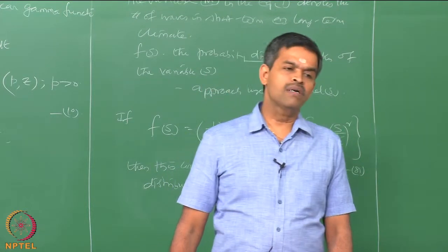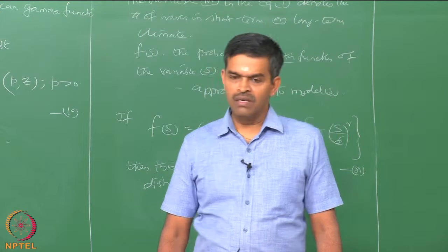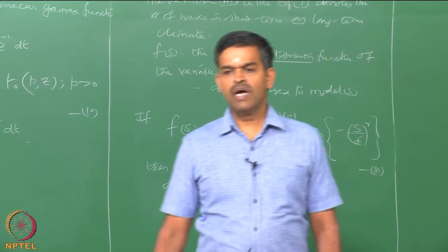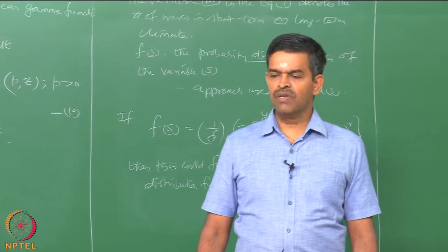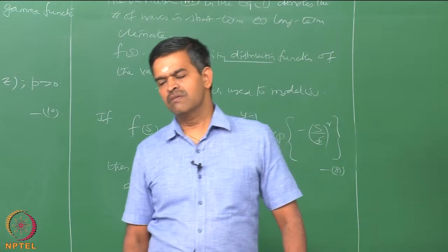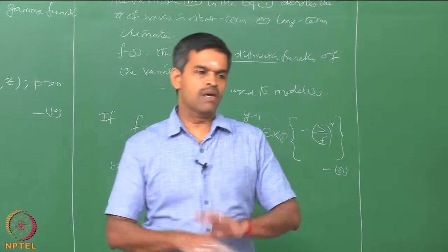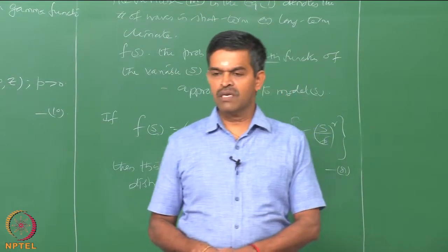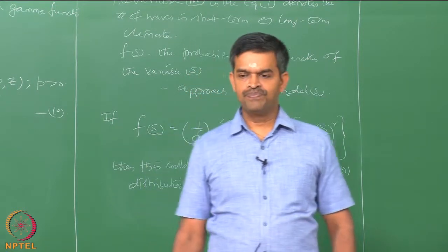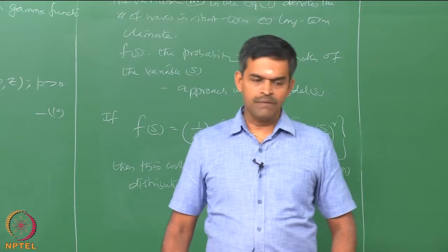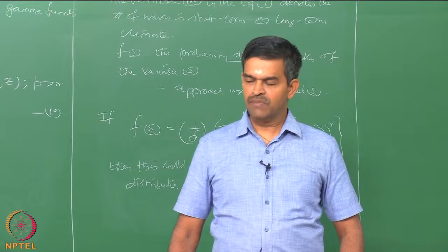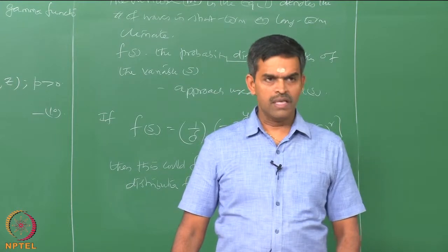Then they are compared with the load carrying capacity, which is estimated based upon the empirical relationships advised by international codes, to actually understand the reasons for these uncertainties. So, as discussed just now, there are many uncertainties which lead to a general statement that fatigue estimates in offshore structures cannot be accurate. They can be relatively better if you start using the experimental models for fatigue damage estimates as well, which we will discuss in the next lecture.